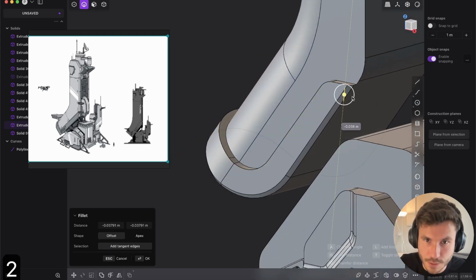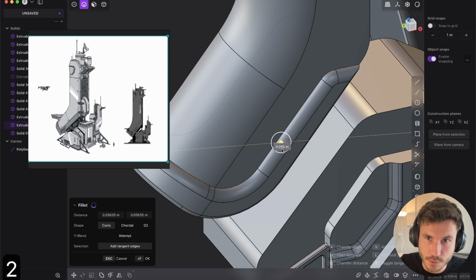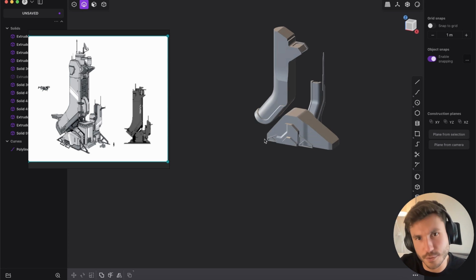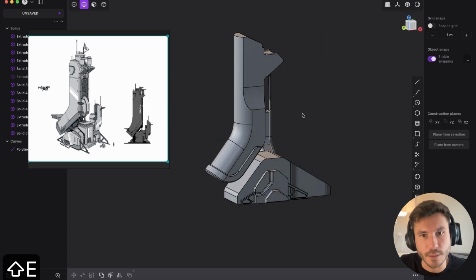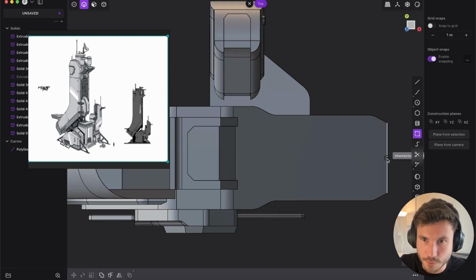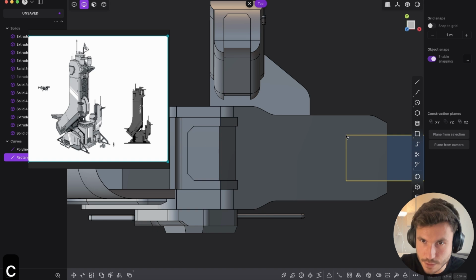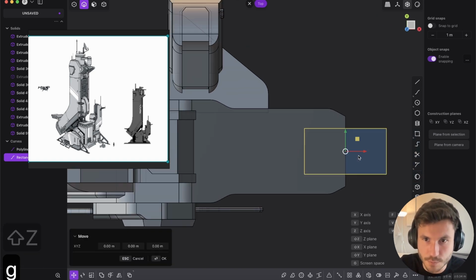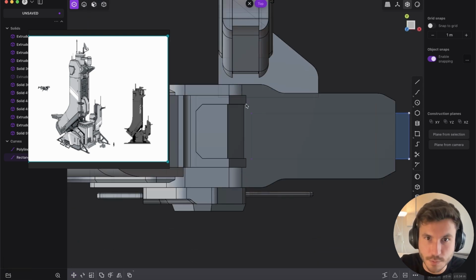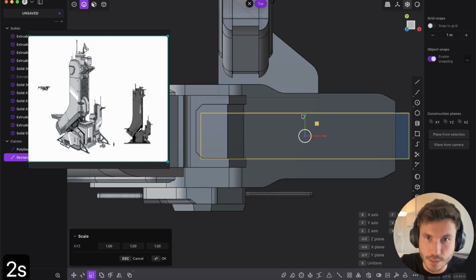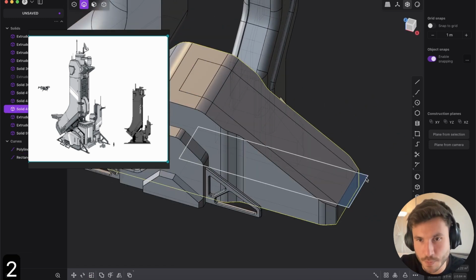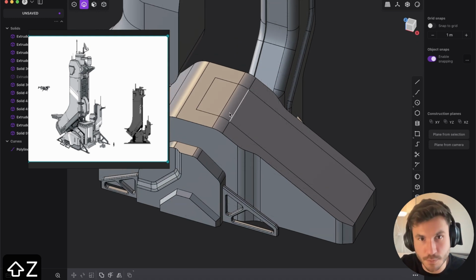Why? Because now we can give here a nice chamfer at the bottom and the top. Something like that. Again, you see, just to give it a little bit of, just some steps. Maybe again, top view, create a rectangle, press C. Okay, we can't see through, so Shift Z and just bring this rectangle now to the top and adjust the points manually. I think that works always much better. So just adjust it and something like that. And just imprint again. So Shift 1, or for you it's the imprint command.